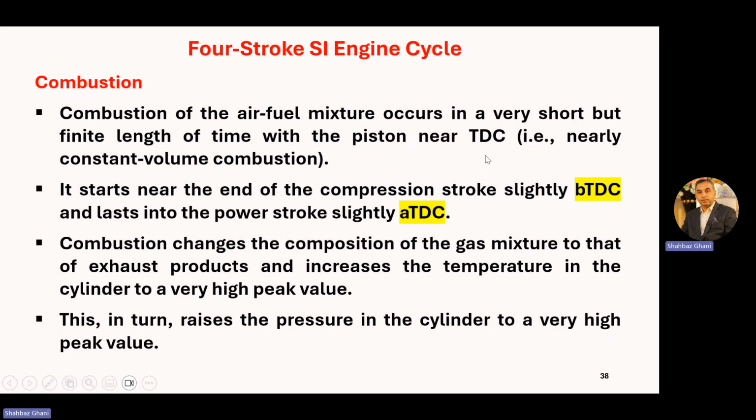So when the piston is reaching TDC, your ignition starts and combustion starts. Piston reaches TDC, combustion is still going on. Piston starts its movement back towards BDC. After a few degrees, your combustion finishes.